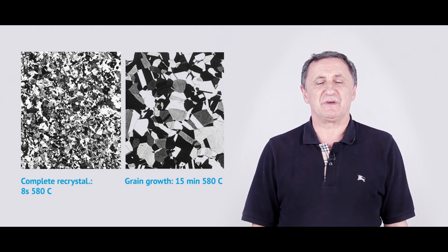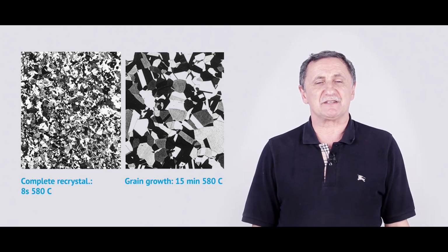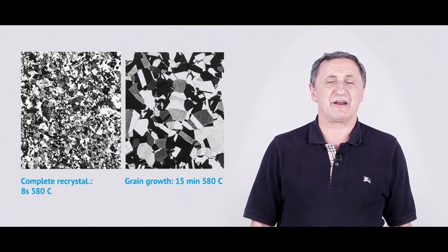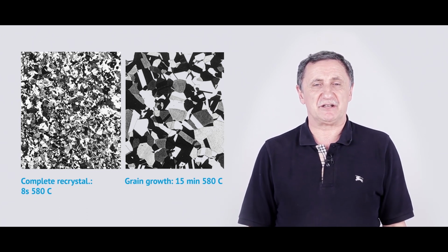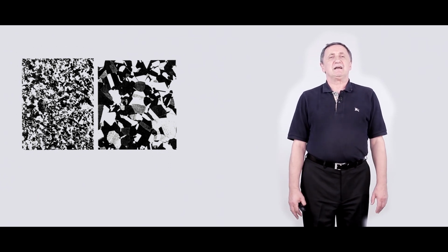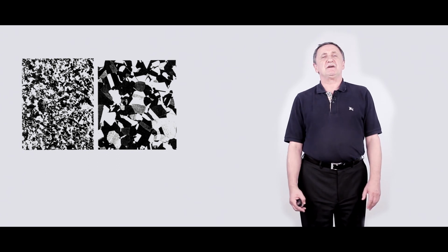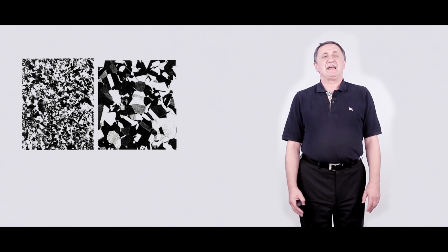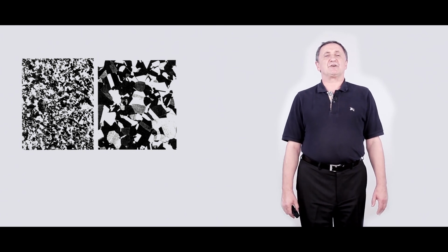So this example, as for me, very nicely demonstrates how we can control the grain size of our material, specifically of metals and alloys, and by controlling the grain size, how we can control the mechanical properties of this material. I wanted to say that grain growth, and this is the last stage of the annealing, occurs again owing to the driving force to decrease system energy by decreasing the grain boundary surface. And so in order to control it more precisely, you have to know the kinetics of grain growth.